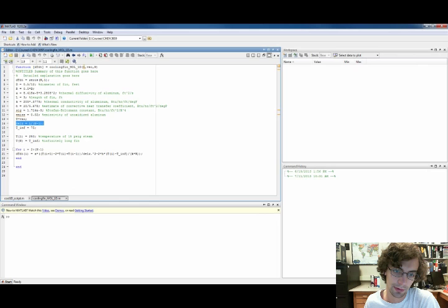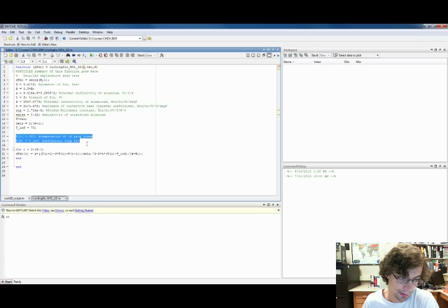Before we get to that, though, boundary conditions. And this is an important one. This is just where you define the thickness of each node, of each basically slice of the fin that you're sectioning up based on your method of lines number of nodes. And these are the two boundary conditions that you'll need, because you'll really need a total of 3 boundary conditions.